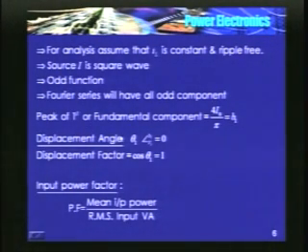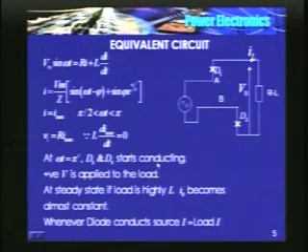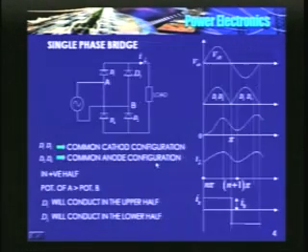Now what is the displacement angle? It is the angle between the fundamental component of the input voltage and the fundamental component of the source current.